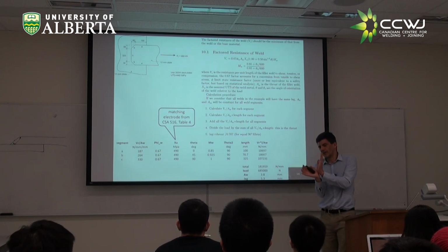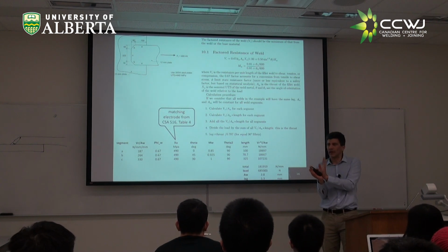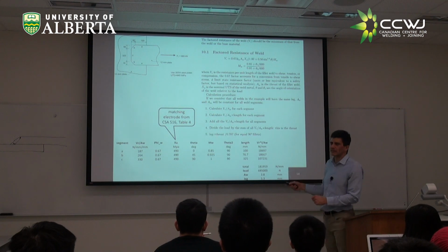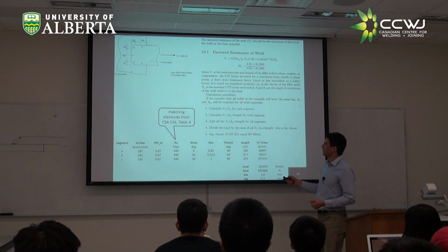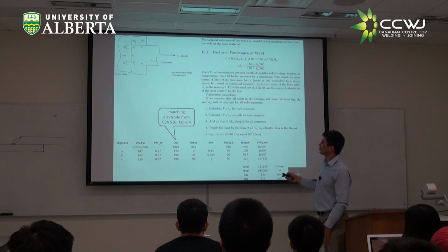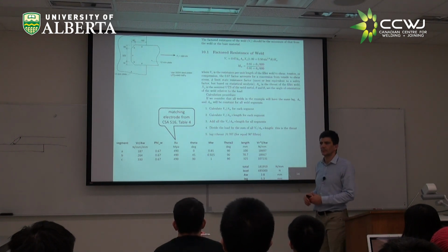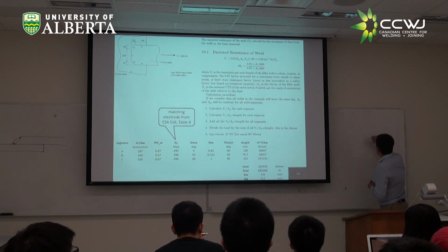Throat, we're talking about a fillet that is equal legs. It would be 45 degrees. So the leg, what we specify in the design, is going to be longer or shorter than the throat? Longer, right? Because, let's see if this works.